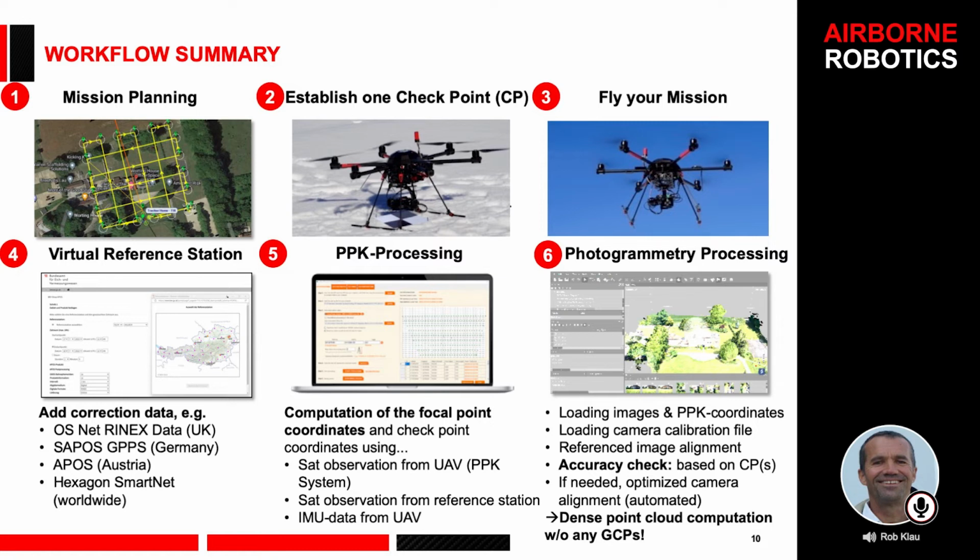You're taking good, clean data in and producing your photogrammetry, and then, as Alex mentioned about point 2 there, if you can have a couple of checks on your site, you're not using them to rubber sheet your data and stretch it and make it fit. You're just saying, okay, on my checks here, I'm seeing that I'm within 2 centimeters, 3 centimeters, 1 centimeter, whatever. You're measuring how well you are measuring. Coming from a surveyor, that is a more solid process, a forward engineering process, than the traditional GCP approach.